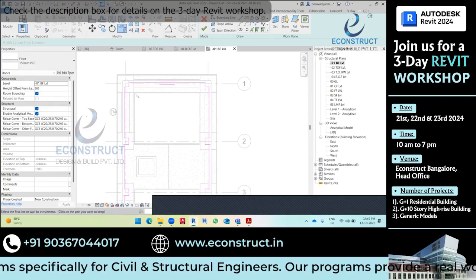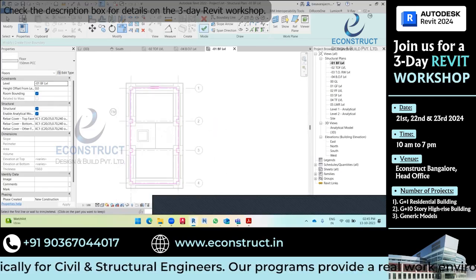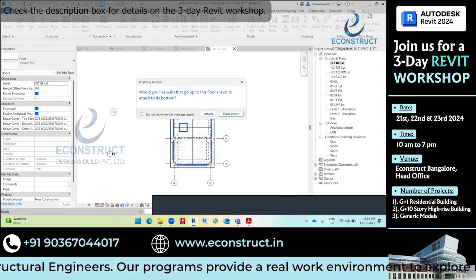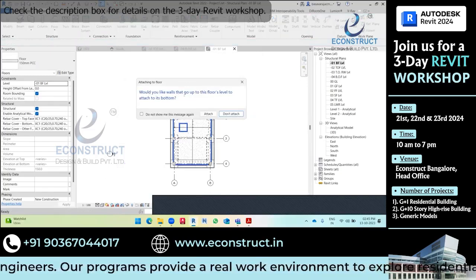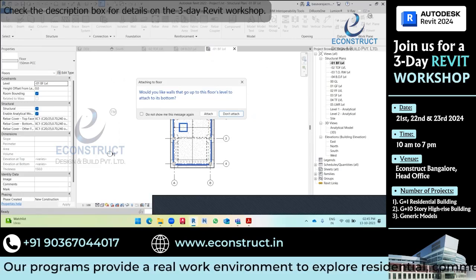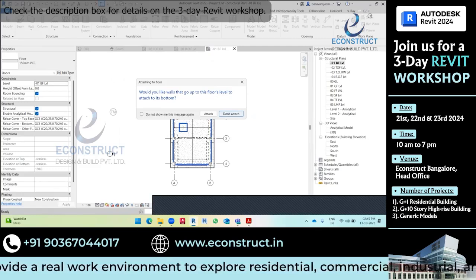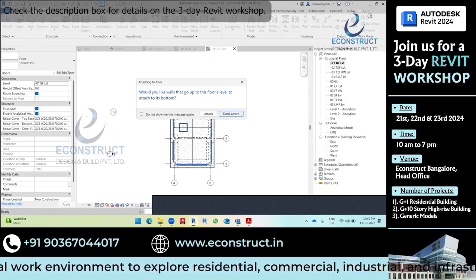Okay, now it is a closed loop. I will click on the finish button. It will ask, would you like walls that go up to this floor's level to attach to its bottom? Click on don't attach. I will explain this later.